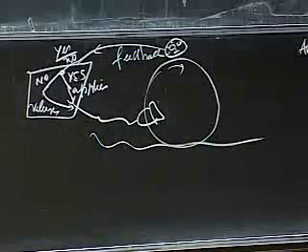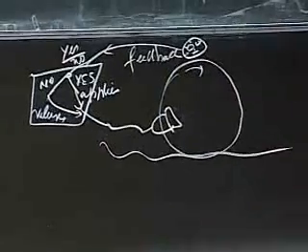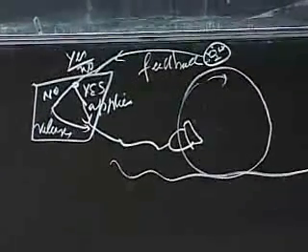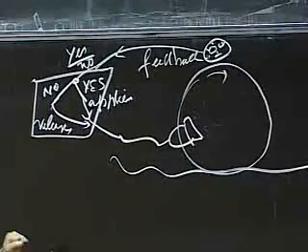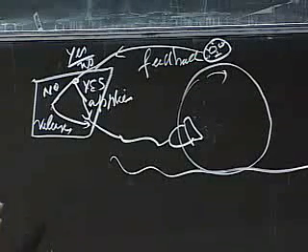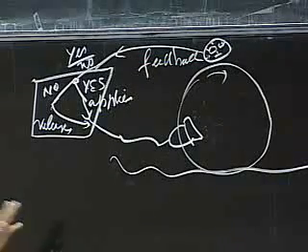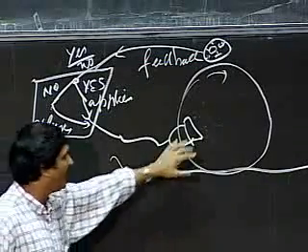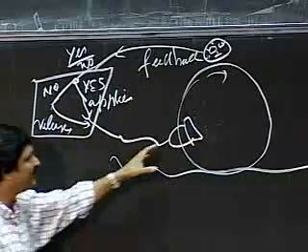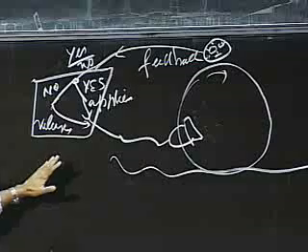So in fact, if you take your car out, let's say you go onto the Charles River in the dead of winter, I don't say you do this, and you drive on the lake and slam your anti-lock brakes on, or on an icy patch, you will notice a constant sound that looks like something is vibrating in there. That's exactly what is happening. Oops, the tire's locked, release the brakes. Okay, wheel's turning, jam the brakes on.